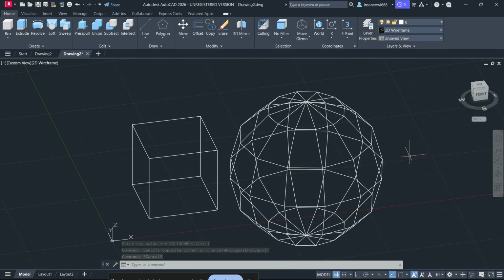Delete complex fillets, chamfers, threads, or tiny detailed features before doing the Boolean operation. These details can often be the reason AutoCAD fails during the merge or cut. Once the main solids are combined successfully, you can usually add the details back afterward. This approach is especially helpful when working with mechanical parts or highly detailed 3D models.